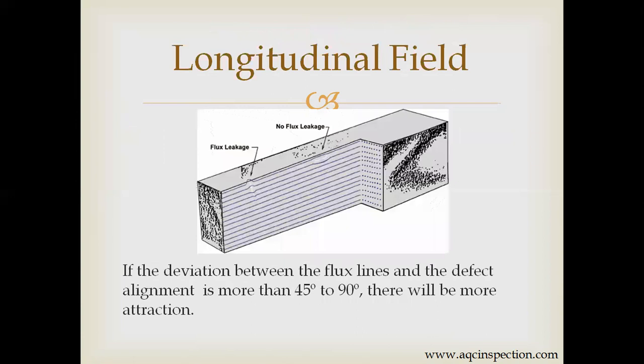Remember, the magnetic field which we produce identifies defects which are perpendicular to it. When the defect orientation is parallel to the magnetic field, the defect cannot be identified.